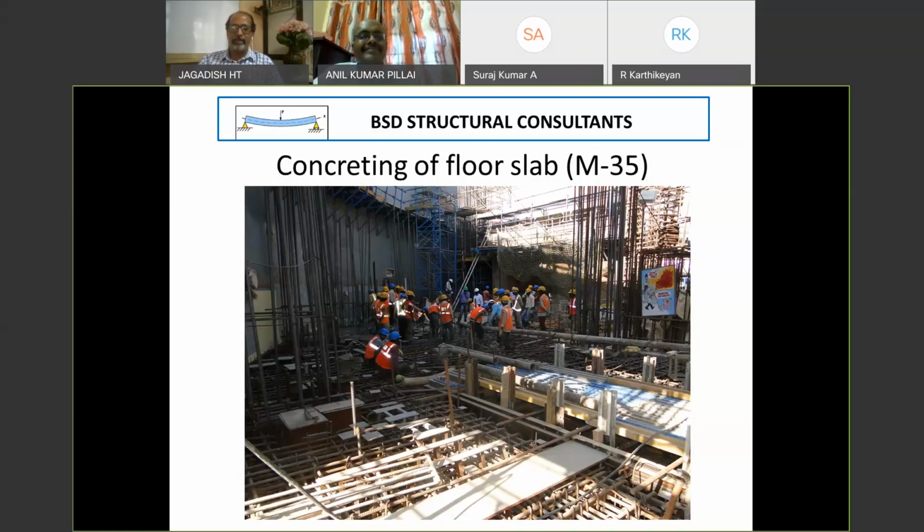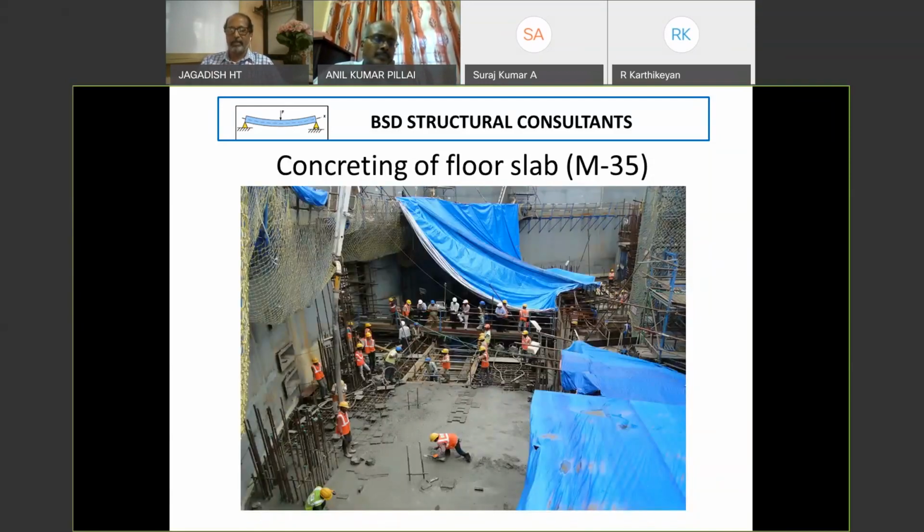So in a reactor building, we try to avoid anchor fasteners and put insert plates as much as possible. We even have anchor bolts installed in the slab. By doing this, we are avoiding anchor fasteners. All the equipment and all the system lines are supported on insert plates.